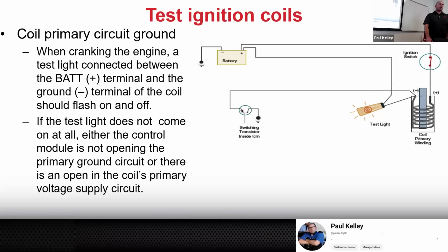Pop the cap off. And you know what we found? That whole ignition pickup, which is like a coil of wire, where that little arm comes around and triggers the sensor, right? Big old bundle of copper all hammered. It's like, oh, Juan, you go to the store and you get the distributor. And he's like, the distributor is a little expensive. I said, no, I know, but that's what's wrong, within just a few minutes of diagnosis. Make sense? He didn't want to buy the distributor. He wanted to buy the spark plugs.